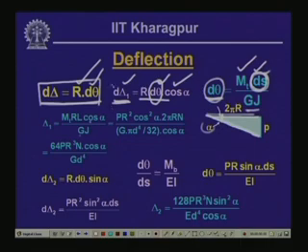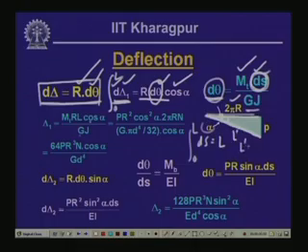So, if we would like to get the whole deflection over the entire spring, it is the integral of d delta 1 from 0 to L, where we have the integral from 0 to L of ds, which is the length. Now, when the wire is wound in one plane, the length of the wire is equal to twice pi r. Because of this inclination, it has taken this particular length. Let us call this length L dashed. So, L dashed cos alpha is equal to twice pi r. L dashed therefore is equal to twice pi r by cos alpha.